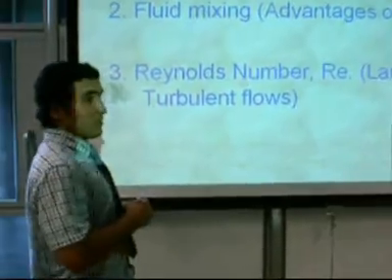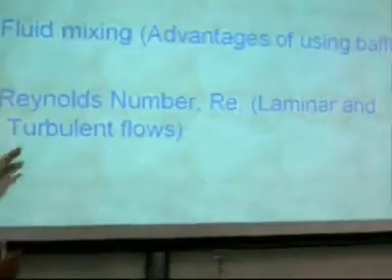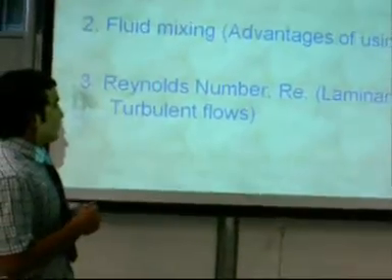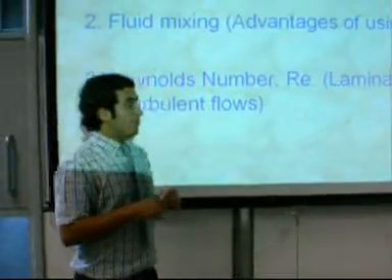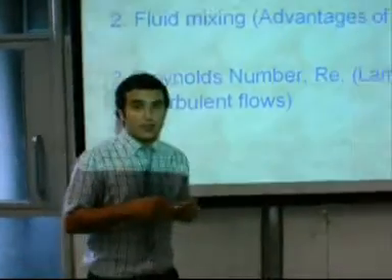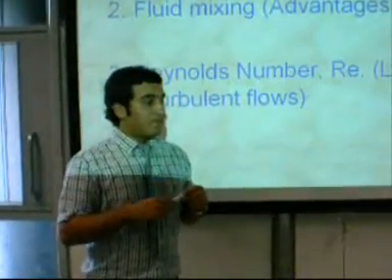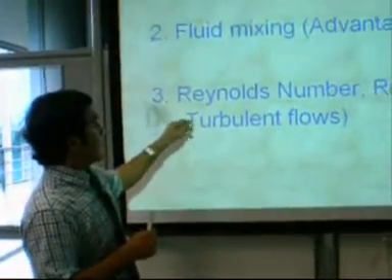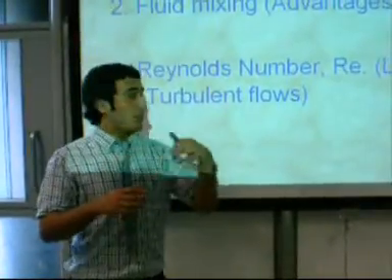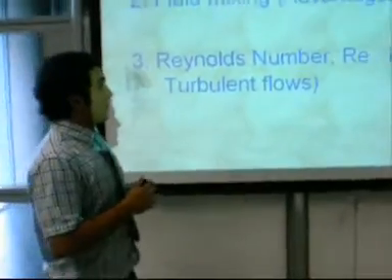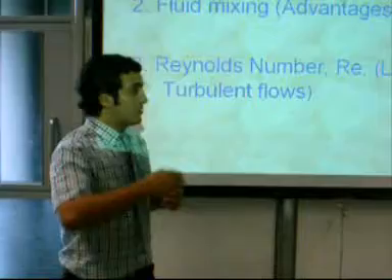The third relation I found is the Reynolds number from chapter 4, incompressible fluids, laminar and turbulent flows. The formula used in this experiment and the formula used in our fluid mechanics tutorial lectures are similar. In the one we use for turbulent and laminar flow, we use the fluid velocity in the straight pipe. But in this experiment, the Reynolds number uses the oscillatory velocity.